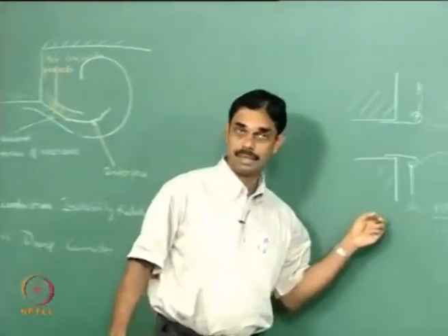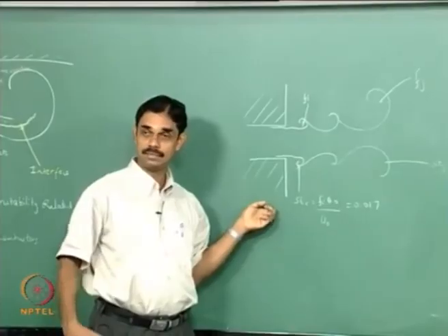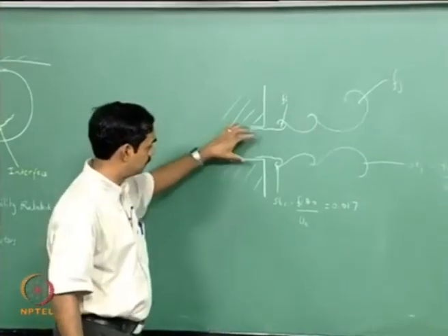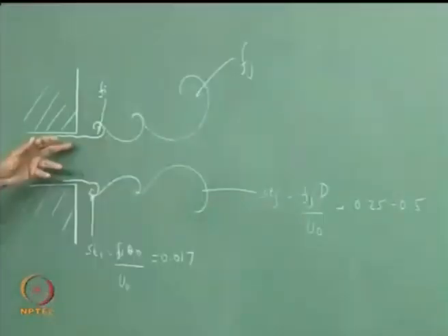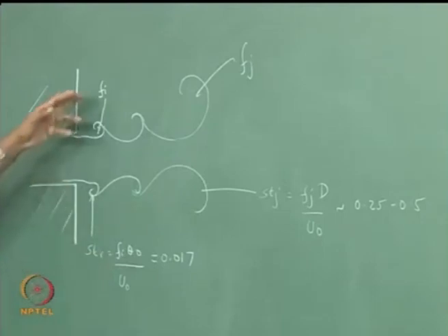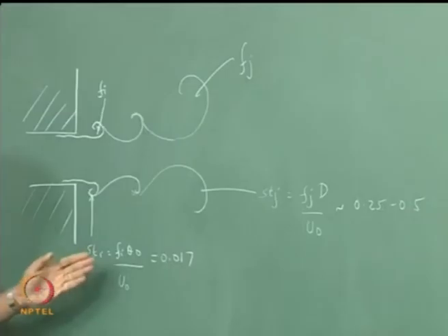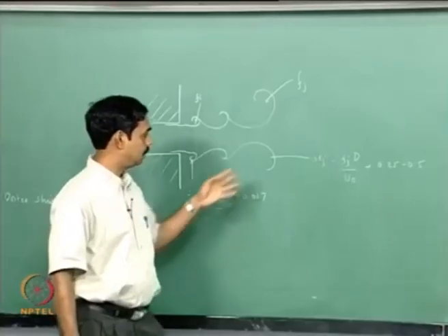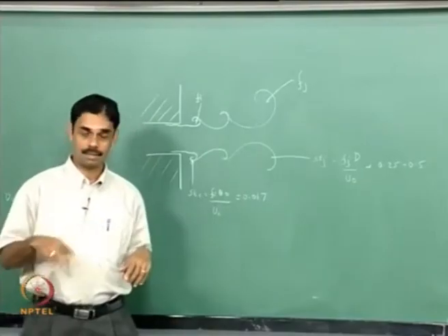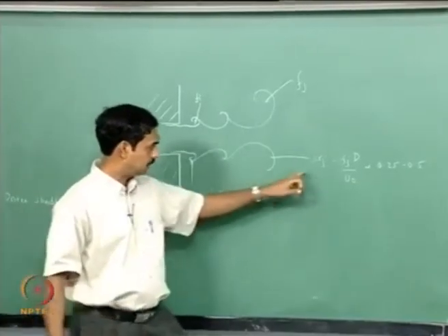And from the basic fluid mechanics of jets, we saw that there are instability waves, and they scale as follows: if the frequency is f_i, where i denotes the initial region, they scale with a Strouhal number based on the momentum thickness at the exit and the velocity at the exit. And of course there will be vortex merger and interaction and so on, and eventually you will have a lower frequency and a bigger vortex, which is scaling like